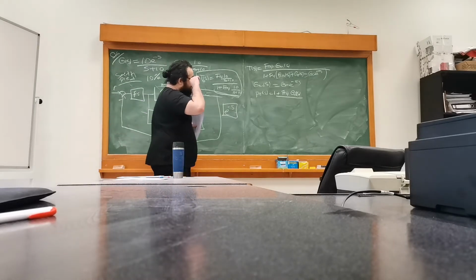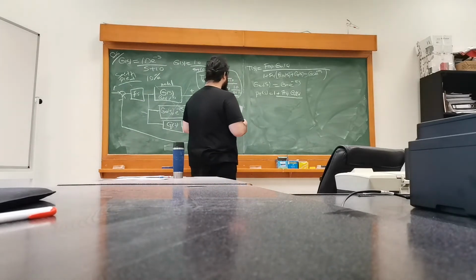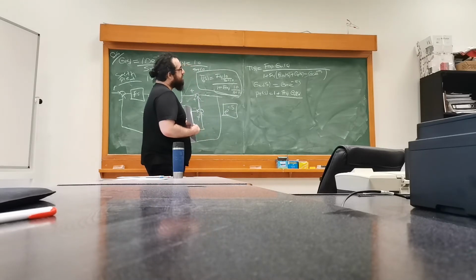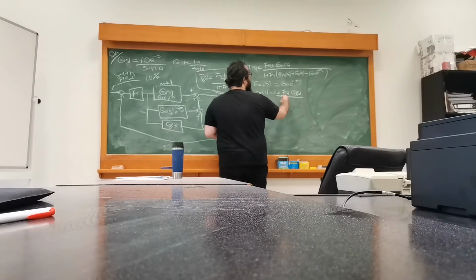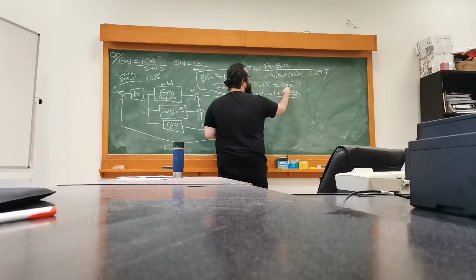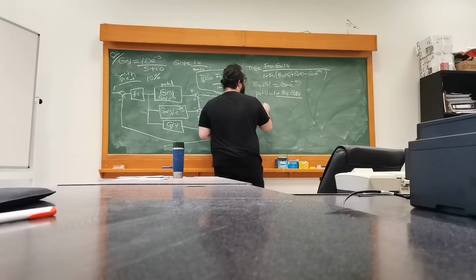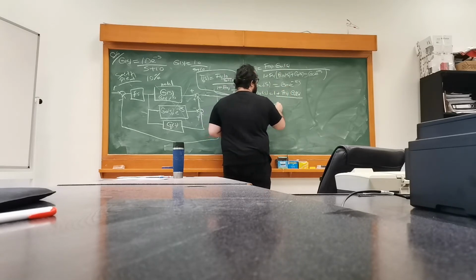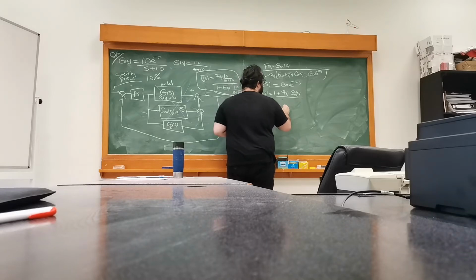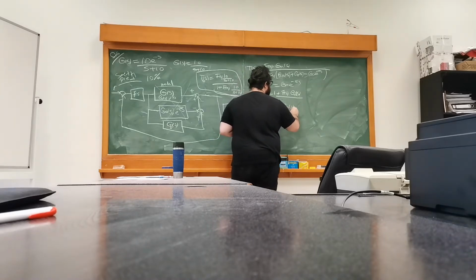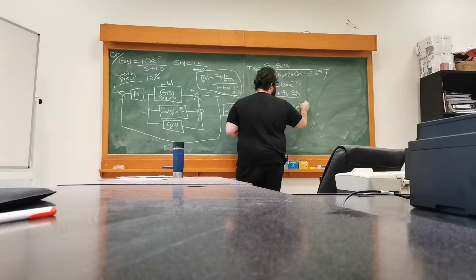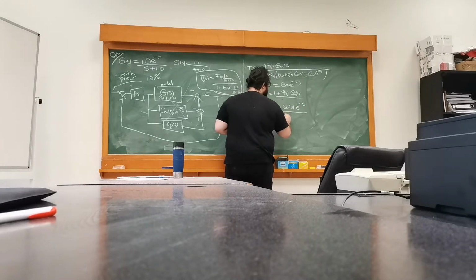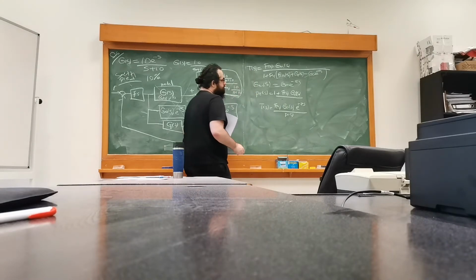That is nice, because this was not the case if you don't have the Smith predictor. If your model matches, you will still have T(s) equals F(s) G0(s) e^(-τs) divided by the characteristic polynomial.